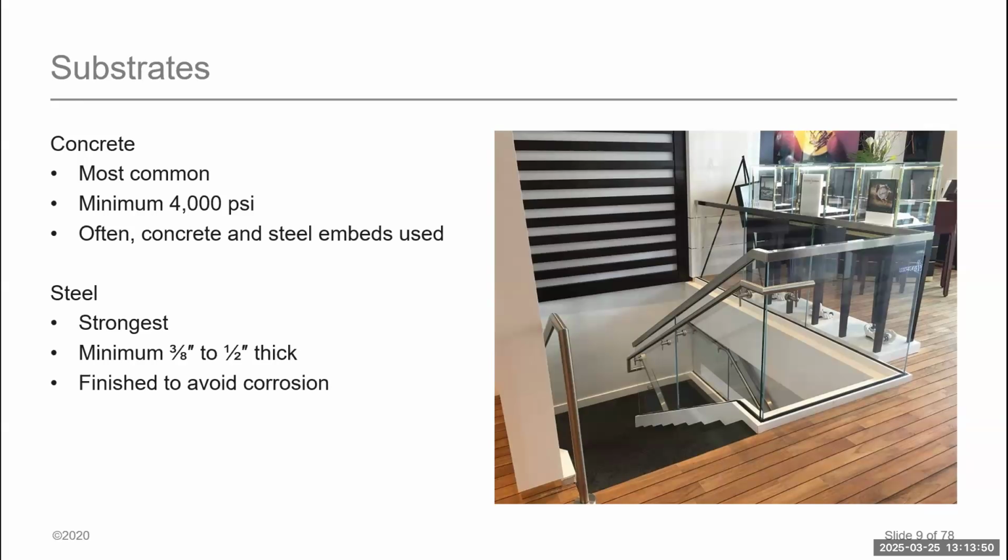When we have a typical guardrail load with a base shoe, we will need to have an embed somewhere around 3.5 to 4 inches into the concrete. So we will need a concrete depth that's anywhere from 6 to 8 inches in that instance.